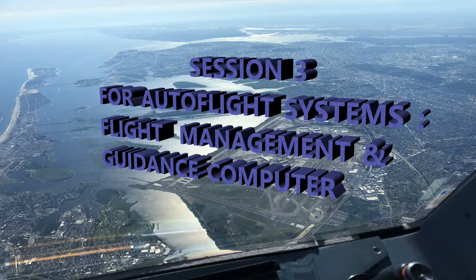The way you're going to access this function, you can do it from the main menu, or from the last leg report, previous leg report, or AFS test. These are different options. You're going to be selecting from the troubleshooting data option. So from the main menu, on the troubleshooting data option, the FIDS generates a page for selecting the BITE that you want to look at. Depending on what you're working on, that's how you can do that. And then on selecting that troubleshooting data option, the FIDS directly presents the context of the fault which is being displayed, and the computer which identified the failure.